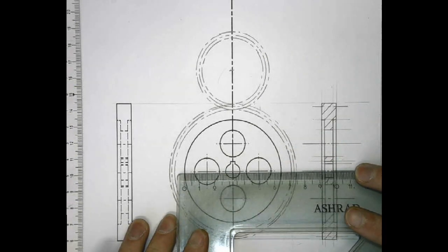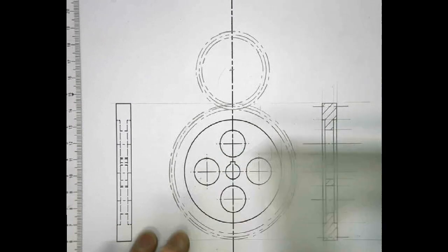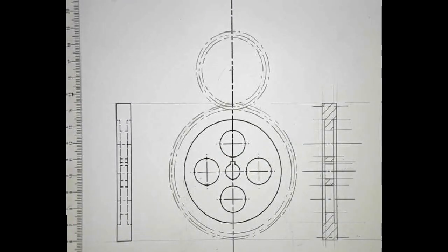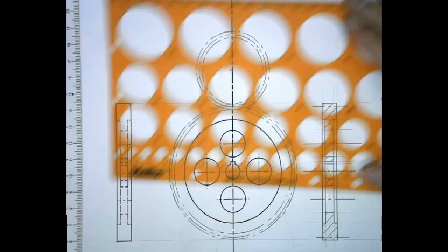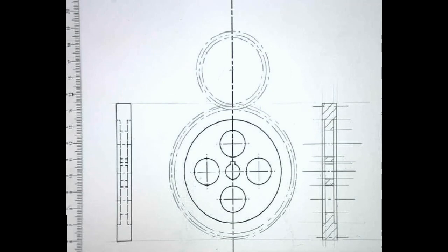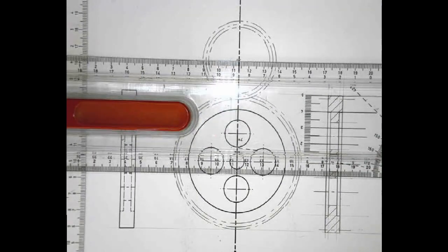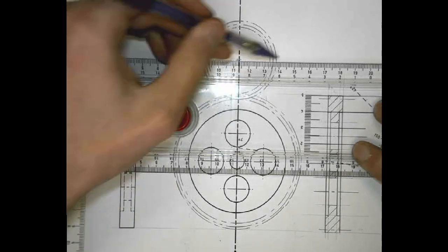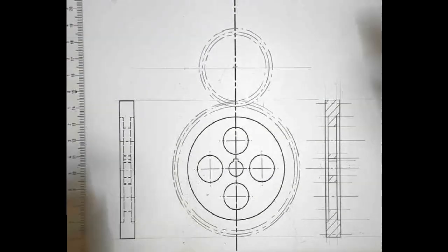So when we measure off this body diameter, we get 64 millimeters in diameter. So we'll be looking at a 32 millimeter diameter circle. Luckily, on our circle template, we do have a 32 millimeter diameter. So we'll just construct our horizontal center line, and then we'll use our circle template to create the rest of the drawing.